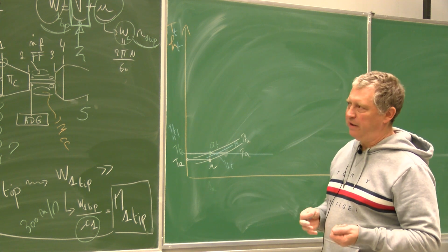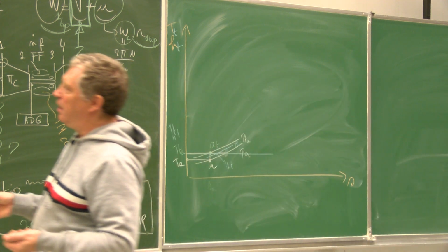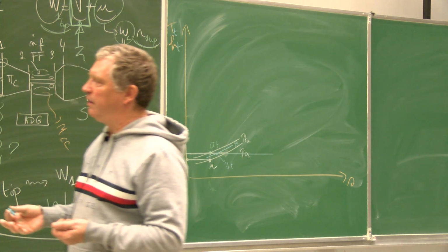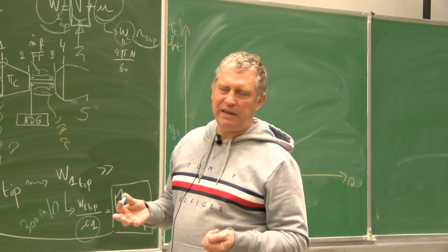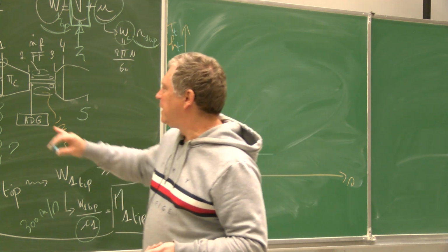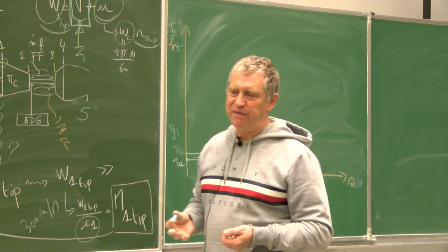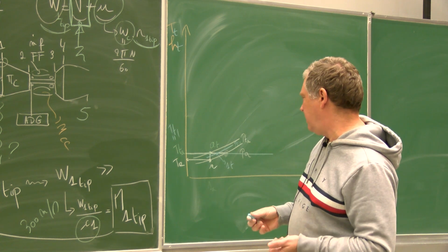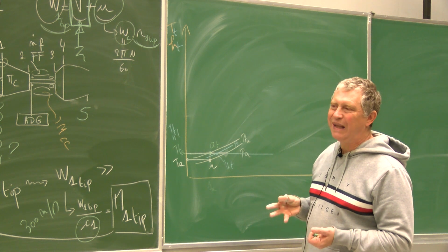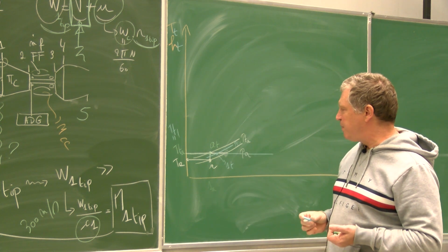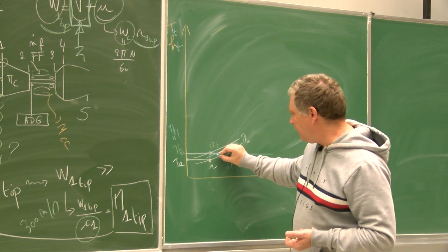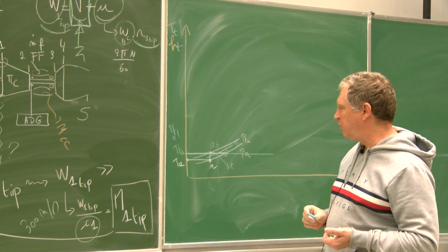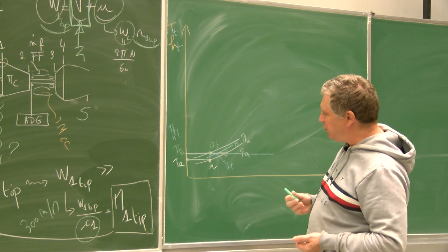And you see that you could also try to look at what is the value of P1 and the value of T1 by considering that TT1 is equal to TTA, and that we know the new PT1, and depending on the M1 that you are considering, let's say you take M1 equal to 0.5, 0.55 as an assumption, or you know better values, and you can characterize also the point 1 static, but it's not easy to represent this point 1 static there. The only thing you can say is that this will be on a vertical line here with the same entropy, of course.